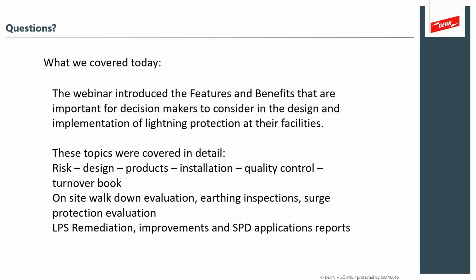Is there a maintenance aspect of SPDs that needs to be considered? Well, that's why the monitoring of the surge protection device is important. In a high lightning environment, an SPD is stressed far more often. So both the selection of the SPD type and suitable maintenance programs to monitor the SPD health are important.